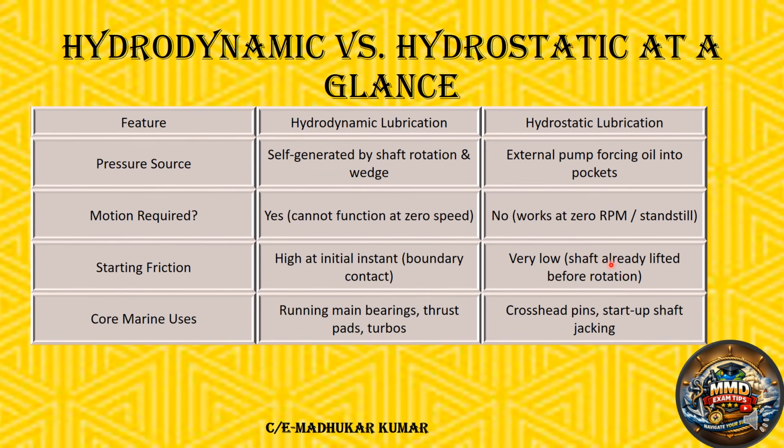Because the shaft is already lifted before the rotation happens. And the core marine uses: running main bearings, thrust pads, and turbos for hydrodynamic. Crosshead pins, startup shaft, and the jacking or lifting of the shaft for hydrostatic. So these are some of the differences, just as an overview.